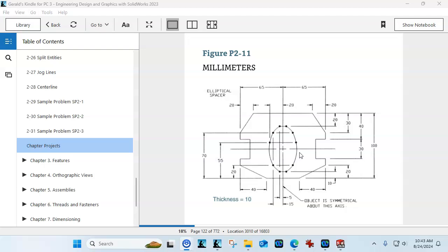It's been a while. The style spline in SolidWorks now has a tangent projection, and you can drag those lines with it. I prefer the standard spline where we just get a node and we get the handles to drag and do that geometry.